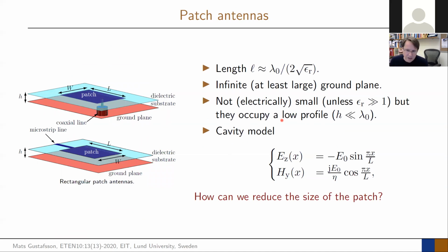So your favorite antenna, I mean, you all designed your patch antenna. Half of you had also measured the radiation patterns of yours, and the rest will do it in January. So you know quite a lot about your patch antenna. And what's really the fundamental understanding of your patch antenna comes from this cavity model. And in that one, we got out that we had a typical length, which is half a wavelength in the substrate of the patch. So it means it's half a wavelength size.